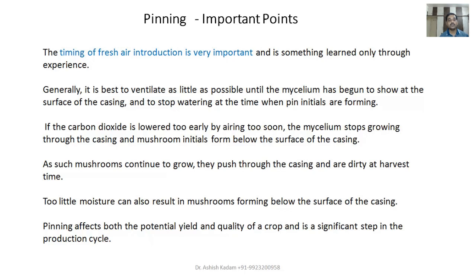So how will you do this? If you have the technology, the right design in place, the right ducting, supplying the air at the right places. Just having ducting does not mean you have the right circulation of air. The ducting has to be designed in a proper way. The air velocity in the duct, and at the holes of the duct from where the air comes out, has to be at the right velocity and right pressure.